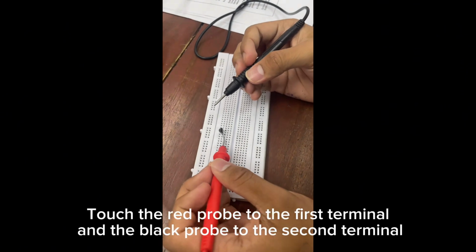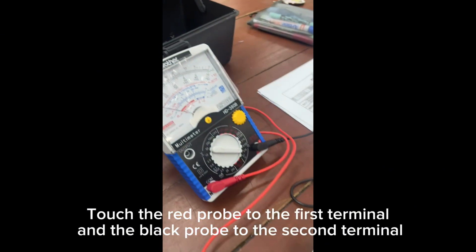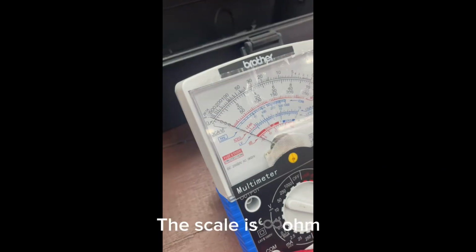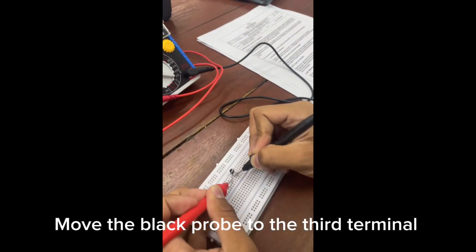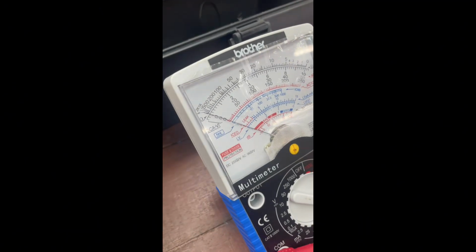After that, touch the red probe to the first terminal and the black probe to the second terminal. The scale is infinity ohm. Then, move the black probe to the third terminal. The scale is infinity ohm.